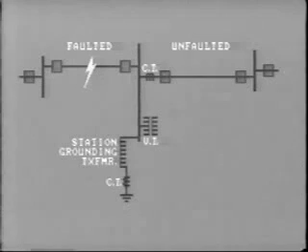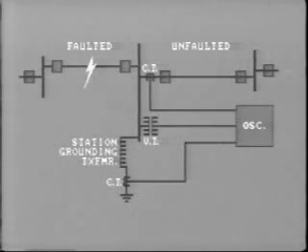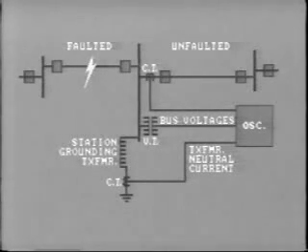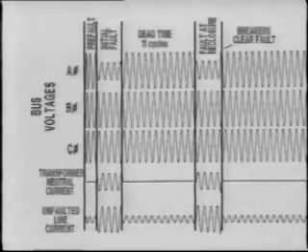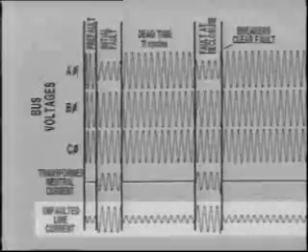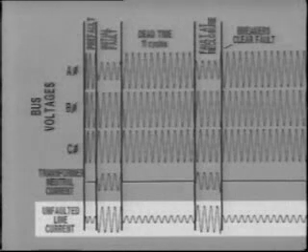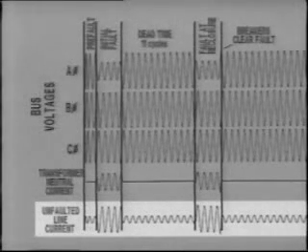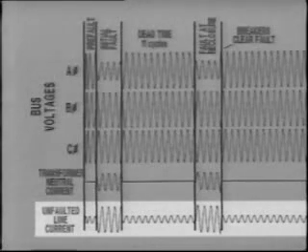In practice, this happens quite frequently when the line does not stay de-energized long enough for a temporary fault to clear on its own. In this example, the oscillograph has captured the substation bus voltages in all three phases, the transformer neutral current, and line current for one of the transmission lines. The oscillograph system in use here can record 3 cycles of pre-fault data. From the trace of line current, you can see that the line we have monitored is not the faulted line. This is obvious since the current resumes its normal load level after the fault is cleared.